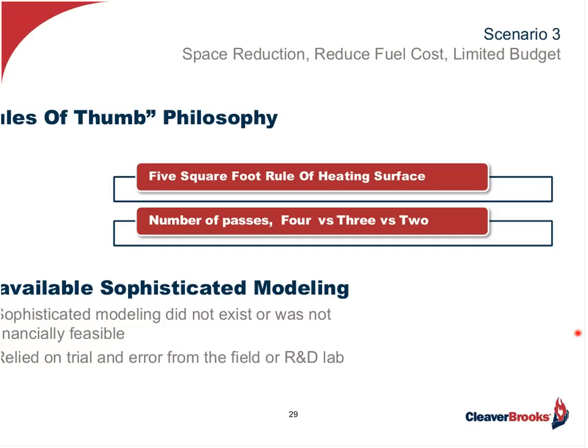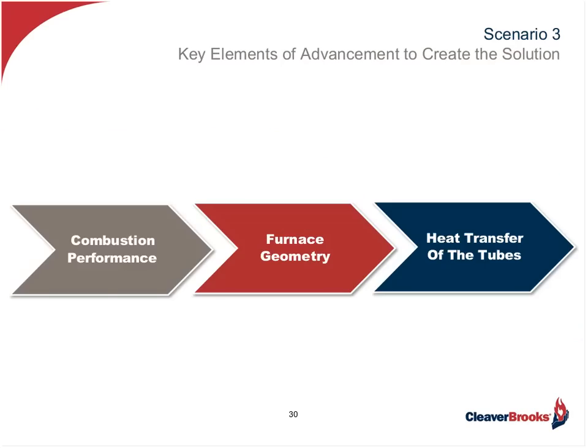What we're looking at, rather, are boilers that are smaller because our customers are asking for this. They're lighter in weight, and they're more efficient. Can you believe that, huh? What we've done, by using computational fluid dynamics and finite element analysis, is construct boilers properly matching the furnace with the burner itself, and then the other heat transfer surfaces, convective and conductive heat transfer taking place in those areas.